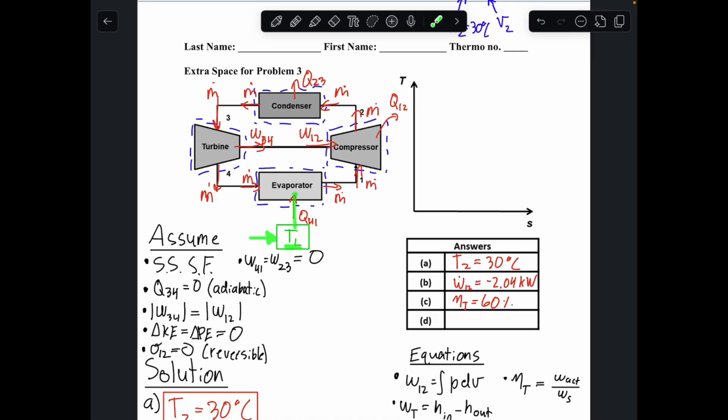So we want to remove as much heat as we can from it. So this Q from 4 to 1 is going to be equal to our QC because we are removing this heat from our low temperature reservoir. And this is the goal of our cycle, to maximize this QC term. So that's what appears in the numerator of our performance parameter.